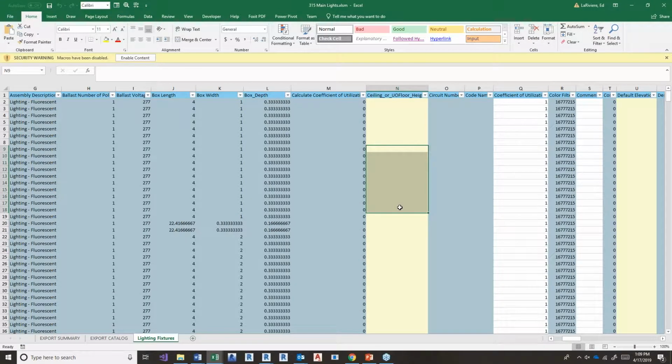And importantly, yellow columns indicate parameters which exist on other families of the same category, but not on the current family. So this would be an important QA/QC check if I'm creating schedules inside of my BIM model, and I'm concerned that all of the light fixtures have the correct parameters associated to them.